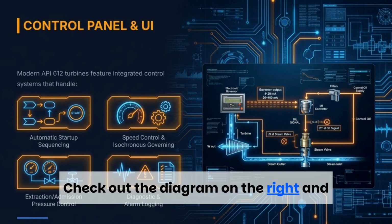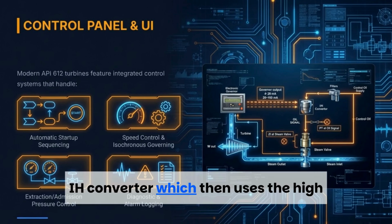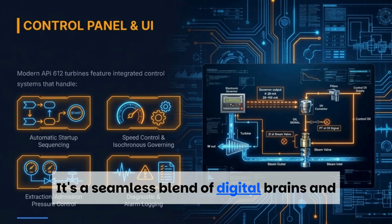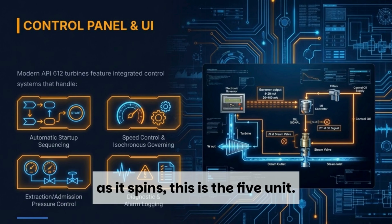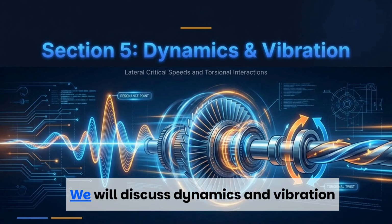Check out the diagram on the right and see that electronic governor. It's sending a 4 to 20 milliamp signal to the I/H converter, which then uses the high pressure control oil to move the massive steam valve in milliseconds. It's a seamless blend of digital brains and hydraulic brawn. If you want a turbine that thinks as fast as it spins, this is the UI you need. All answers for high speed control are right here on this screen.